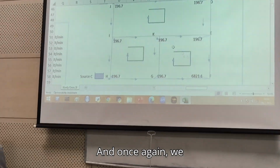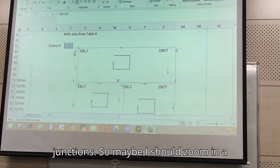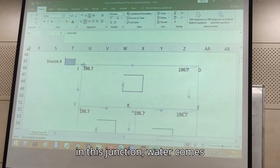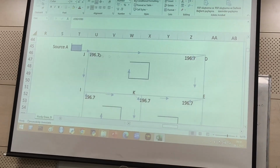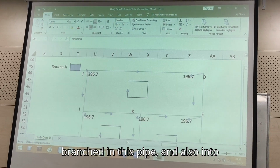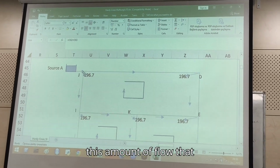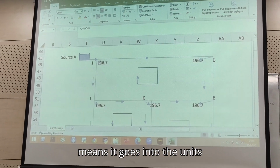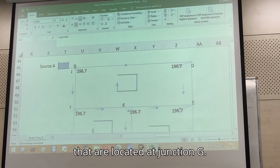And once again, we write the demand flow rates at junctions. So maybe I should zoom in a little bit more. In this junction, water comes from source A, then it is distributed into two parts, right? It's branched into this pipe and also into this pipe. But it also has this amount of flow that goes into the system. Actually, it means it goes into the units that are located at junction G.